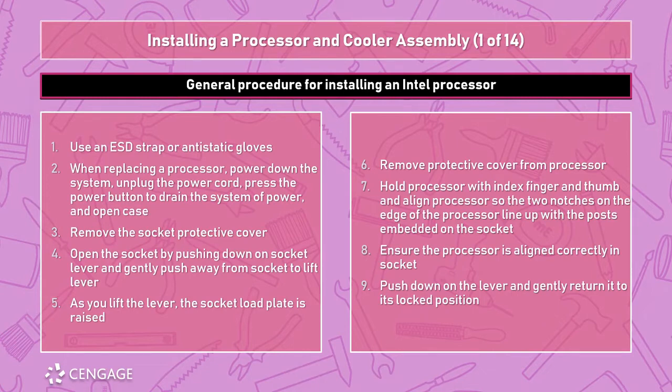Once we've got it set into the socket, it should just kind of gently rest on it if it's Intel. The pins are only if we're dealing with AMD. Once it's in the socket correctly, let's go ahead and gently push the lever back into position, lowering the load plate and locking it in place.